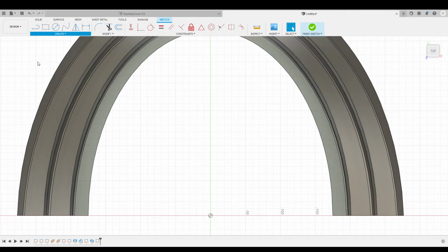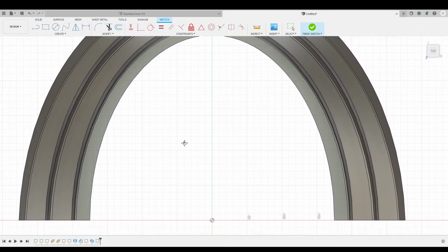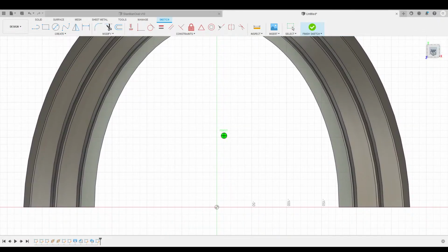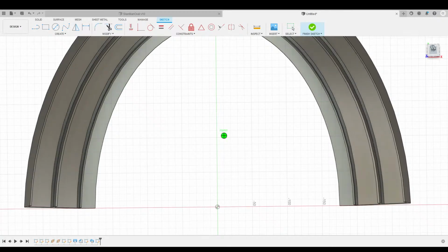Now we are going to create text, and we're going to create text on a path. So we're going to select our path, and we got a few different ones to pick from. I'm actually going to, here, let's cancel that. I'm actually going to project, so this is going to show kind of what project is doing a little better. I'm going to project one of these overhangs.